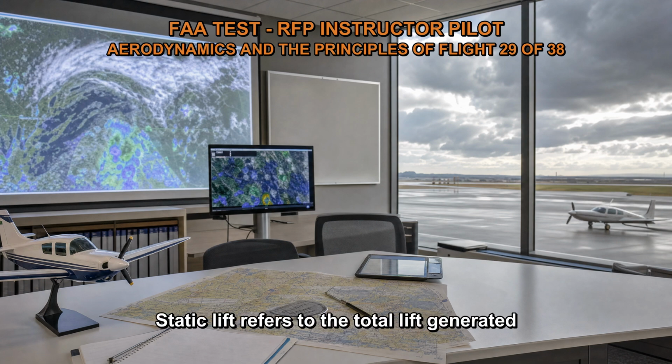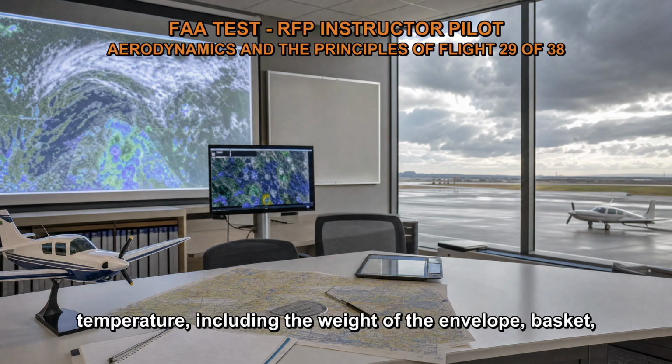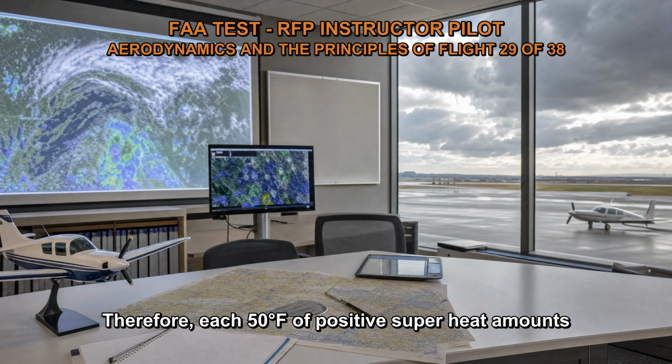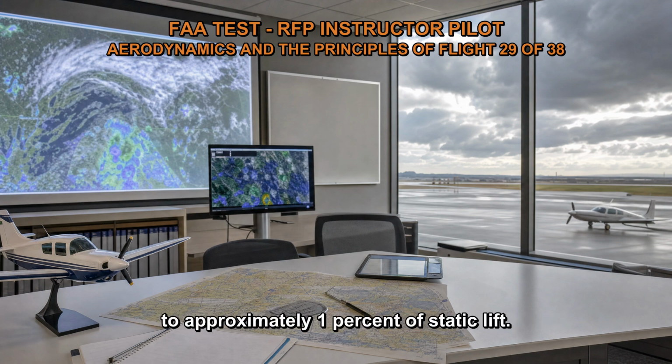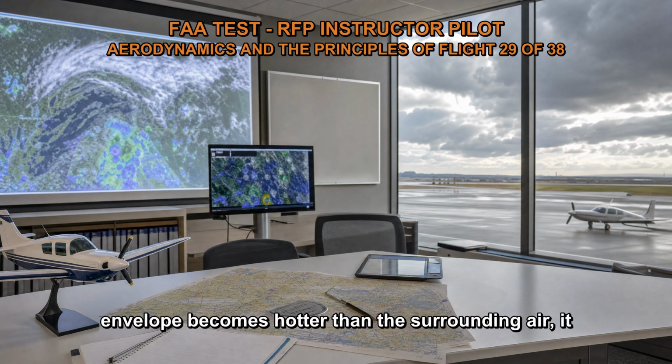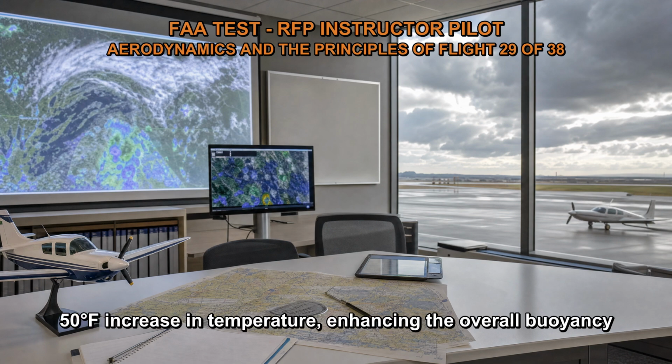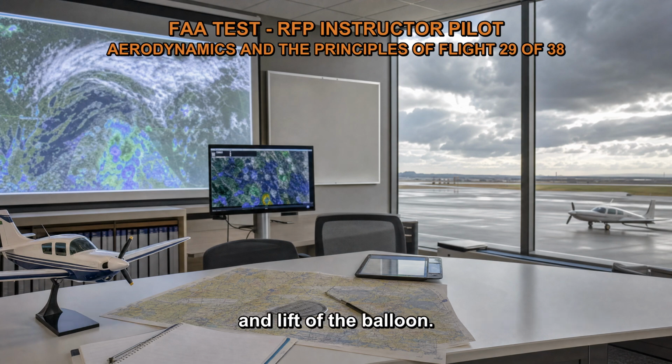Static lift refers to the total lift generated by the balloon at a specific altitude and temperature, including the weight of the envelope, basket, payload, and any ballast or fuel. Therefore, each 50 degrees Fahrenheit of positive superheat amounts to approximately 1% of static lift. This means that as the air inside the envelope becomes hotter than the surrounding air, it contributes an additional 1% of lift per 50 degrees Fahrenheit increase in temperature, enhancing the overall buoyancy and lift of the balloon.